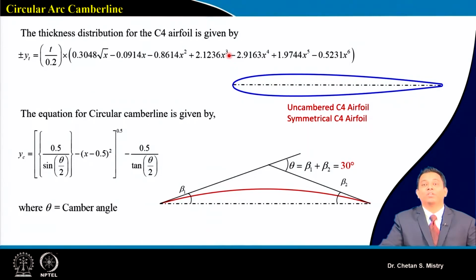Now, as I told, a few aerofoils are available in open literature. So when you are starting with your initial design, or your initial calculation for making a blade, you need to select those kinds of aerofoils first. Suppose you have the equation available for a C4 kind of aerofoil, then on this straight line, this symmetrical aerofoil gives the variation of my thickness. It says at 40% of my chord, I have maximum thickness.